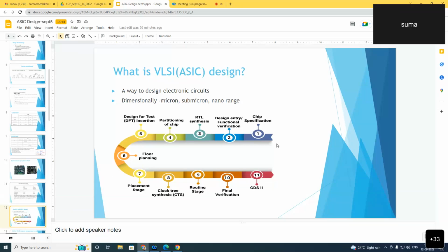As we know, there are two kinds of power that need to be looked into, the dynamic and the static or leakage. Dynamic power dissipation can be affected by the following factors: the VDD, the material used, switching, short circuit current, clock gating, and then operations such as isolation and all.